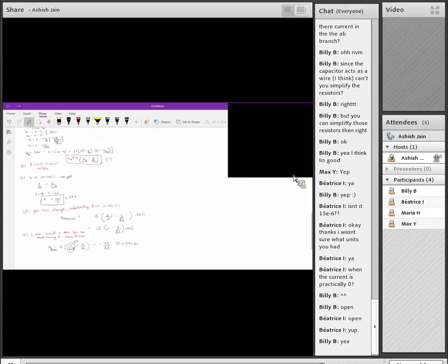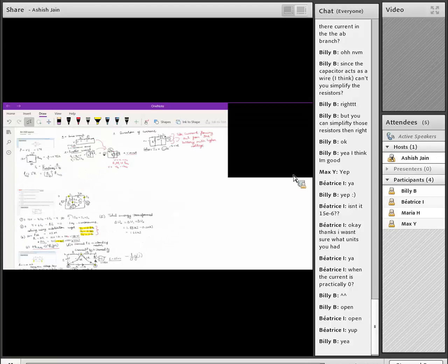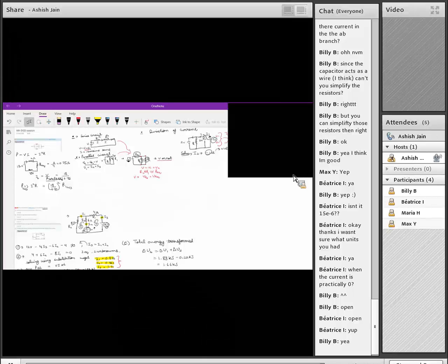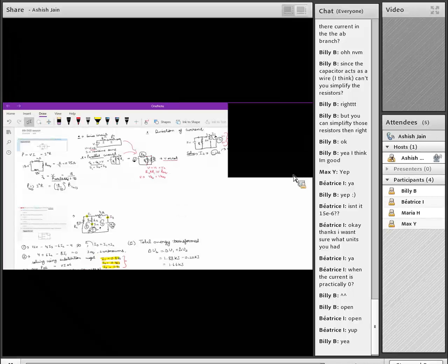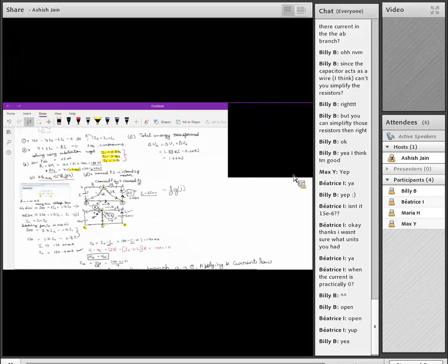Okay, perfect. Let me conclude today's session. We solved like 7 questions today. It was a lot. We covered Kirchhoff's current law and circuit diagrams, various configurations, and we solved all the equations based on these 3 tips. In a series circuit, the total voltage drop is the sum of the drops, and the current remains the same. In a parallel circuit, the voltage drop remains the same and the current is the summation of the currents in the branches. And we consider the direction of the current emerging from the battery having the maximum voltage. That way, 95% of the time, you will correctly guess the direction of the current, as you saw today in several questions. That's what we did.